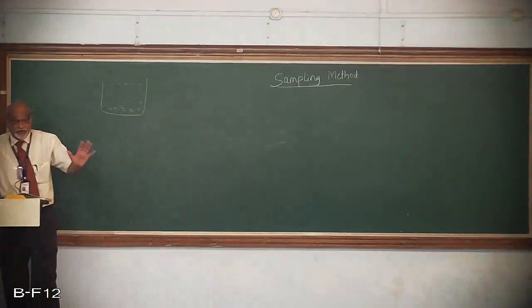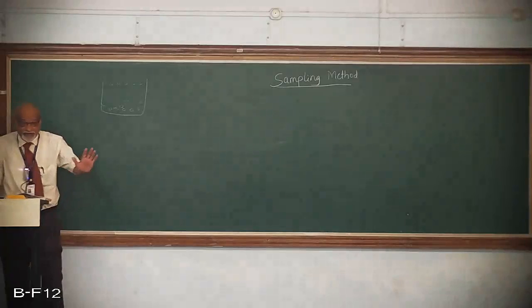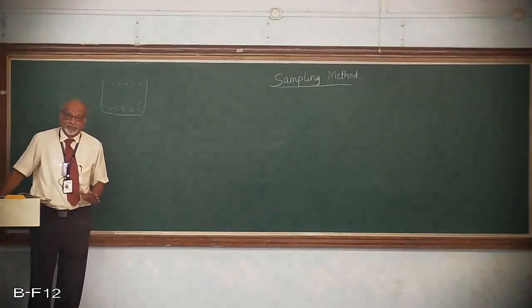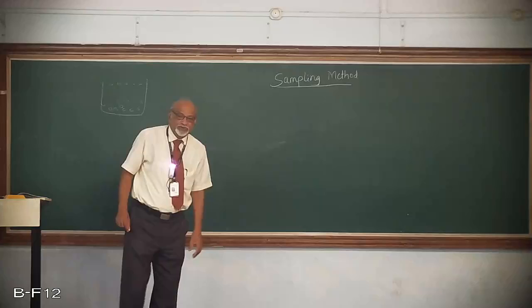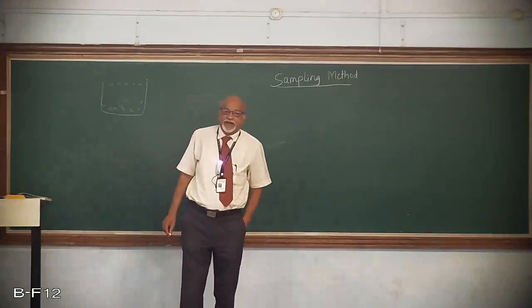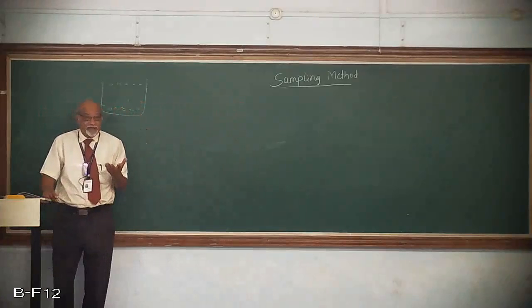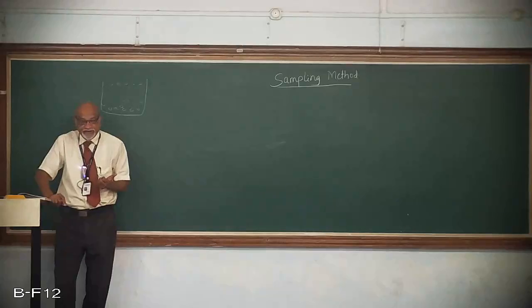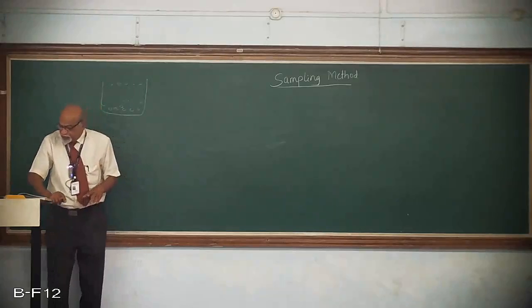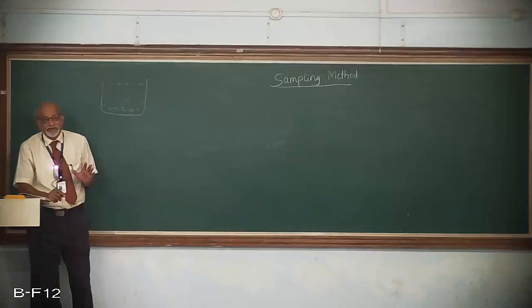That is what is important first, and that is the collection of the sample. Four parts we discussed, is it not? One is randomness of the sample. Second, sample size. Third, quality characteristic to be tested, that means attribute or variable. Fourth, acceptance criteria. And the fifth one is the lot size.